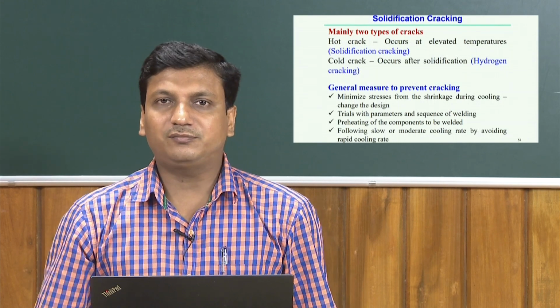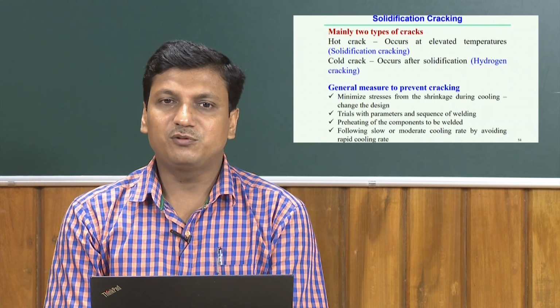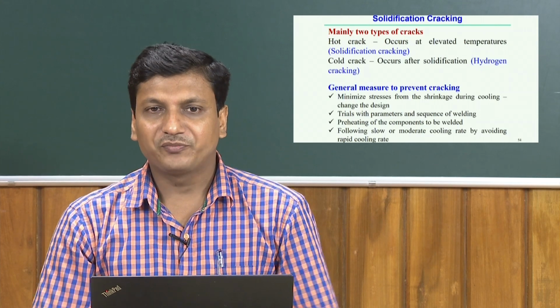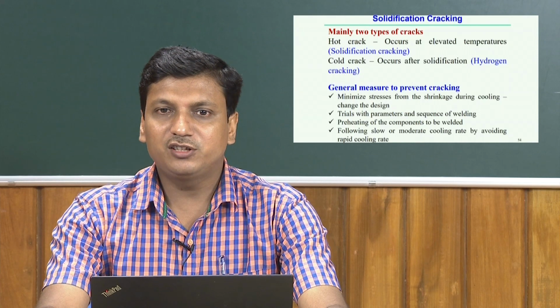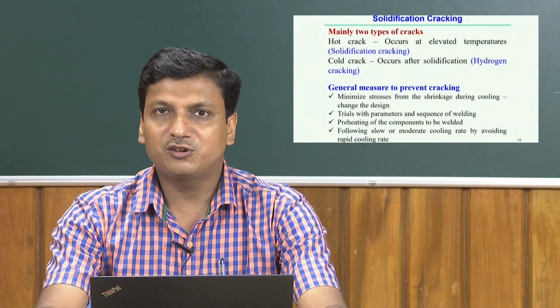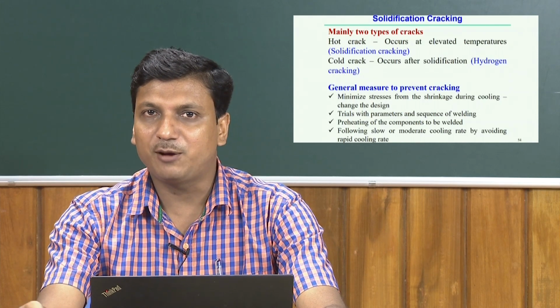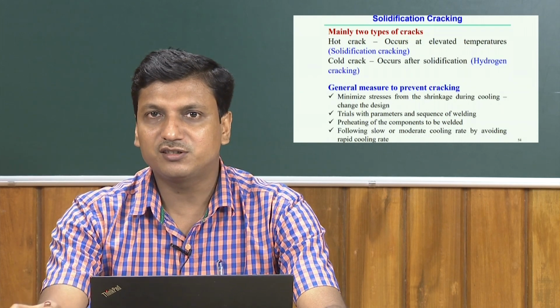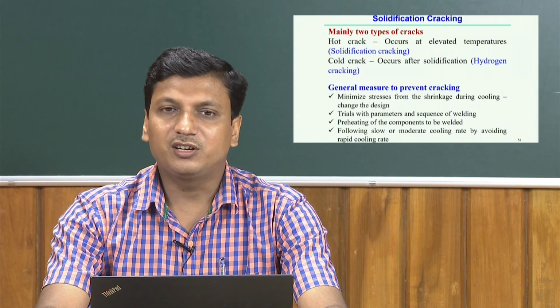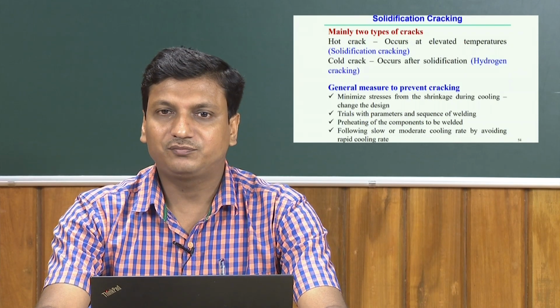It is not always possible to completely avoid the development of stress during the cooling phases, because a phase transformation may happen that, in most cases, induces some amount of residual stresses.